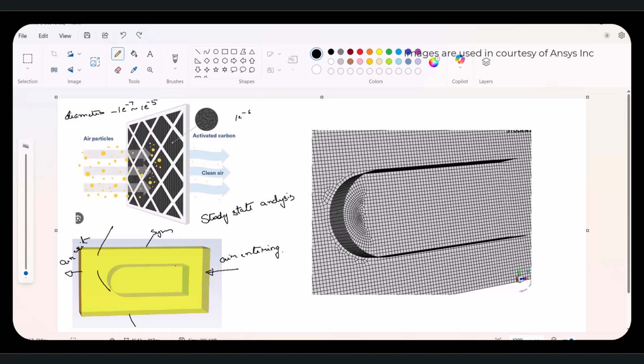So this will be defined as a porous media up to here, and here is the interface from which particles are injected. Any particle coming onto this should either go through this point or stick at this point. This is the particle trap. Anything less than 1e-7 will flow across; anything greater than 1e-7 will be trapped here, right? As time progresses, more and more particles will trap, and they will not allow the air to pass through. So this is a complicated simulation.